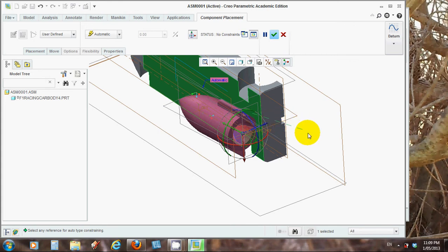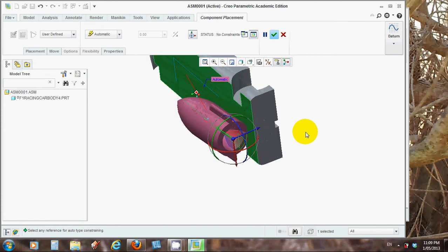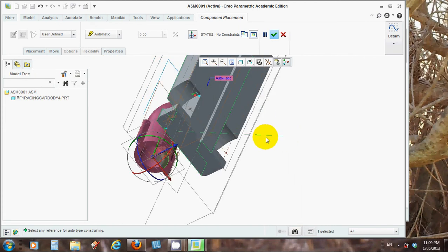There it is. Okay. I want that, and I'm center mouse button clicking now, to join to the top surface, or that flat that I've created on the bottom of the rocket. Almost there. I'm waiting for my computer to catch up.